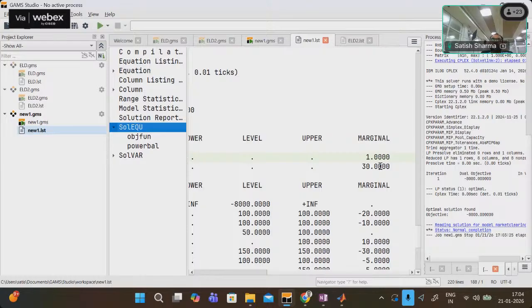So yes, the lambda with respect to the power balance equation, again I am repeating myself, we are going to use this statement multiple times: the dual variable, or the marginal value of the active power balance equation, if the objective function is cost minimization or social welfare maximization, will give you the market prices. If it is economic load dispatch, or market clearing, then it is MCP, and for DCOPF, you can call it LMP. So we will see how LMPs also work.